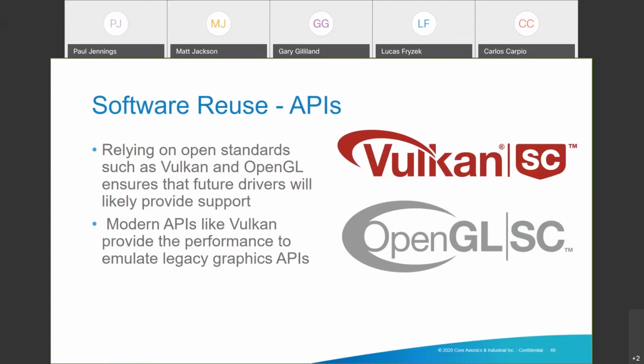With an open standard, anyone is welcome to provide a solution for that graphics API. From a driver developer's perspective, open standards would be things like OpenGL and Vulkan. These are open standards provided by the Khronos Group, but ARINC 661 would be another type of standard that exists higher than the driver level that provides a more open interface to access GPU capabilities.